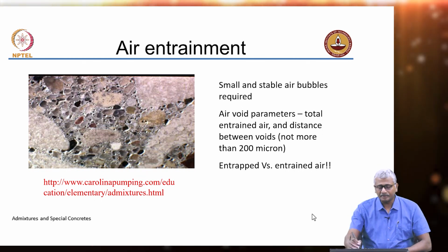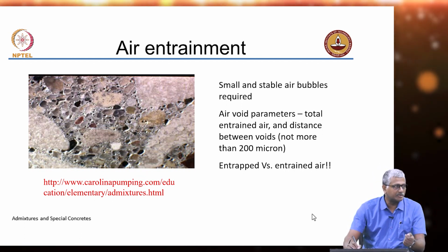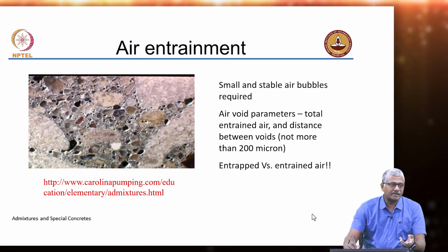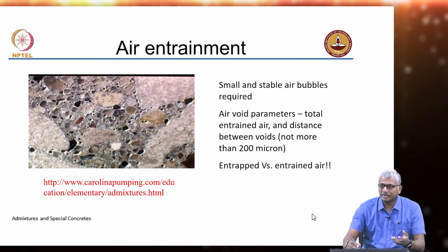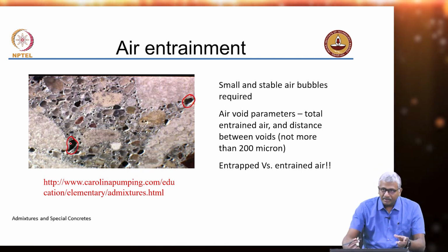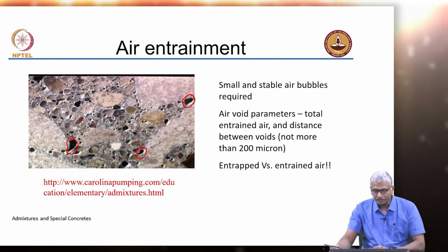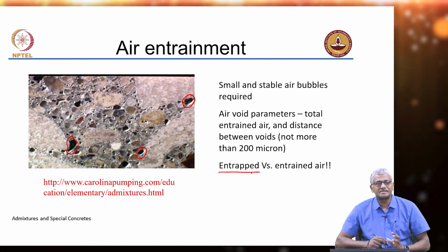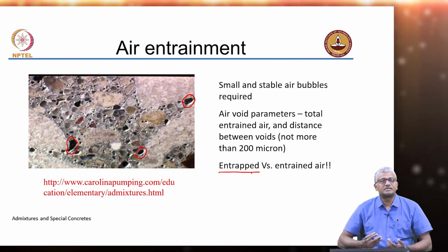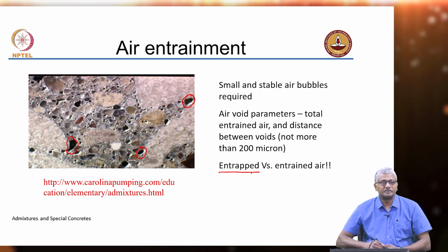And of course, as I said, in OPC, up to 5% of additives or performance improvers are permitted. Performance improvers typically are limestone or sometimes fly ash. These are lowering the overall CO2 impact of the cement. But later we learn that at this 5% level, they are also able to provide additional benefits. As far as cement is concerned, C3S is the major component. More than 50% is C3S, and C3S is also responsible for early strength development.